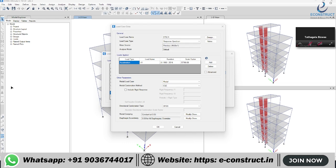If you design a G plus 80, 90 story building, as per the IS 16700 new time period formula, the earthquake would be nominal. Base shear of earthquake would be drastically reduced as per the new formula if you check the tall structure code. Yes, sir. Whereas wind would be predominant, crazy. Understood?